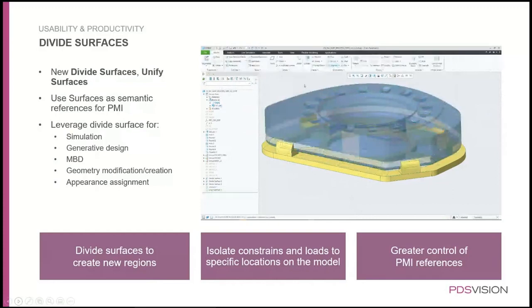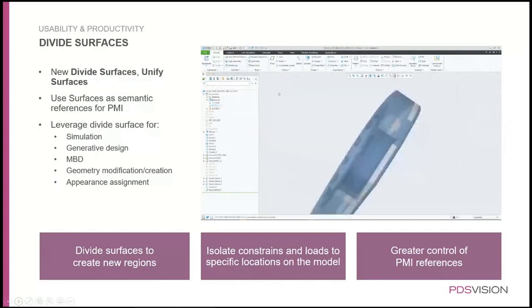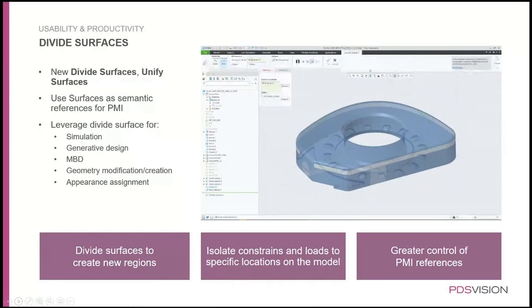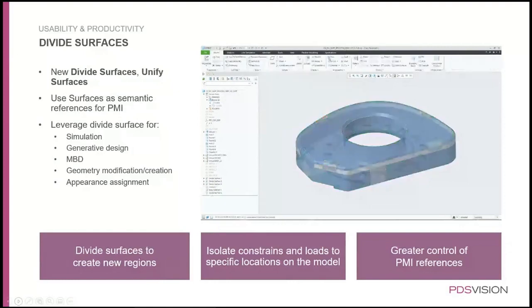Now what we'll do next is hide the jig geometry, and then mark those areas where the jig or tooling is touching with a different color. So what we have there are those intersect curves, which we have already selected, and then you pick the surfaces, basically all the solids in there, and then you select that these will be new ones, and then we give them a color.